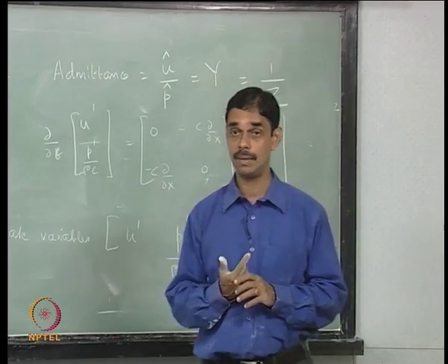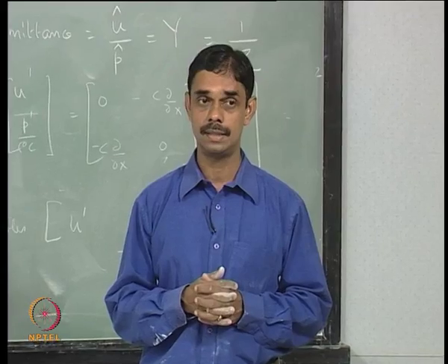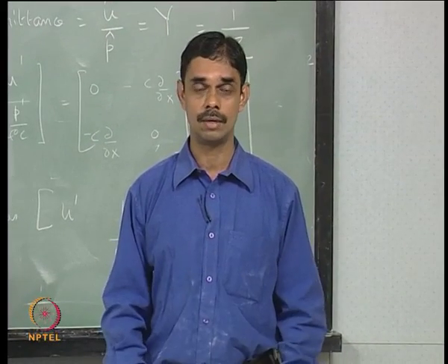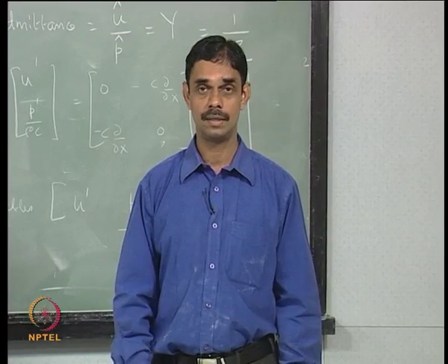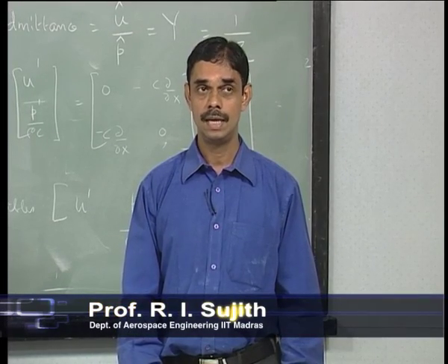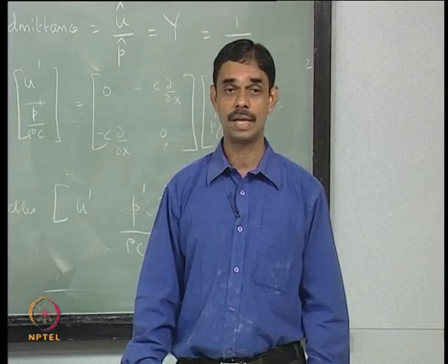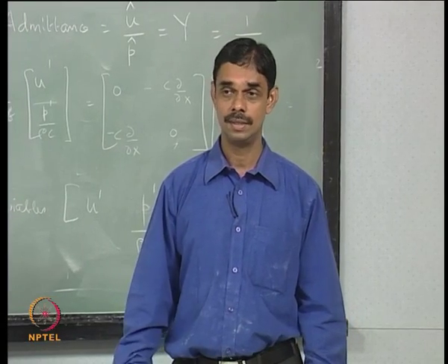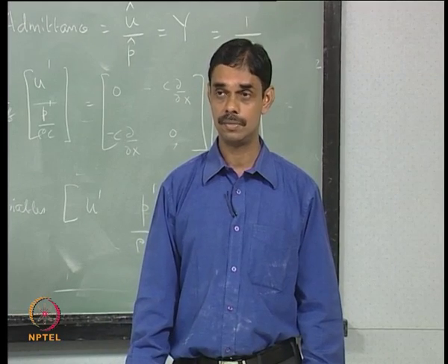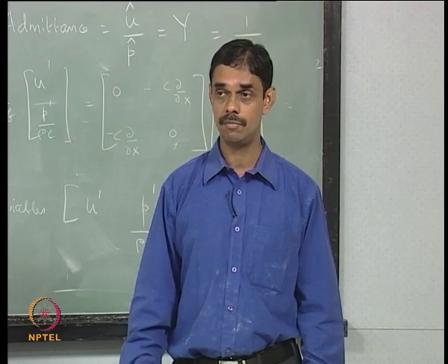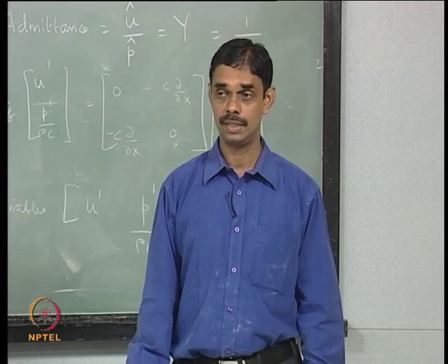So in summary, we have taken a quick look at standing waves in a duct, and we now know how to calculate the natural frequencies of ducts with open ends and closed ends, and we even thought of how this can be used to calculate quick estimates of natural frequencies of even such a complex thing as solid rocket motors. Then we ended with the definition of impedance and admittance, and we will see how that can be used to characterize the growth and decay of acoustic energy in systems.